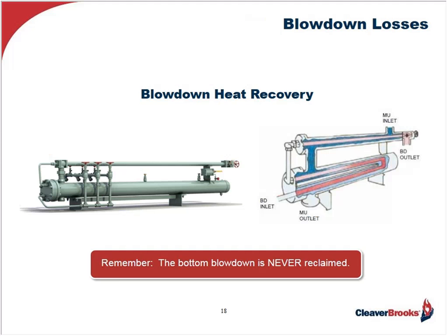Or what about the way the boiler is set up to control the totally dissolved solids in the boiler water, where of course what we're trying to do is maintain the proper conductivity? What's happening to the effluent? Is it going down the drain, wasting these valuable BTUs? It might be a candidate for a blowdown heat recovery system, again putting those BTUs into the boiler's feed water stream before they exit to drain. You'd be surprised at how much payback is possible depending on the boiler size and the percent of blowdown leaving the boiler. Again, something which has to be looked at and evaluated. Not necessarily going to be applied, but it's got to be looked at.